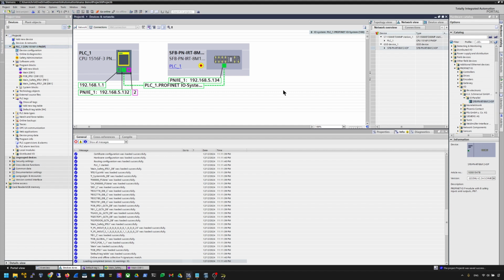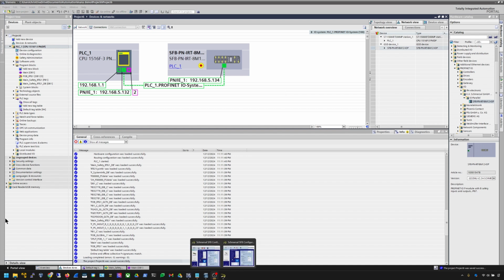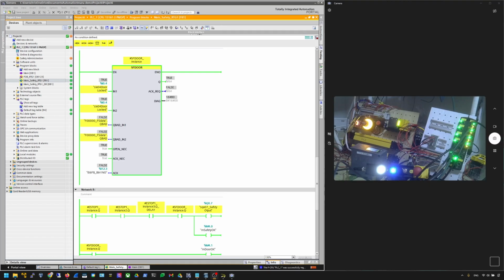So finally, I'll turn on my camera to see the result. Let's turn on the camera. Okay, now we turn on our live camera. And you see the connection is okay, no red lamp, no red LED. Now on the screen, you see the safety output is on. So I will just try to show you in this case to use the control box from Schmersal. Okay, let's see it.